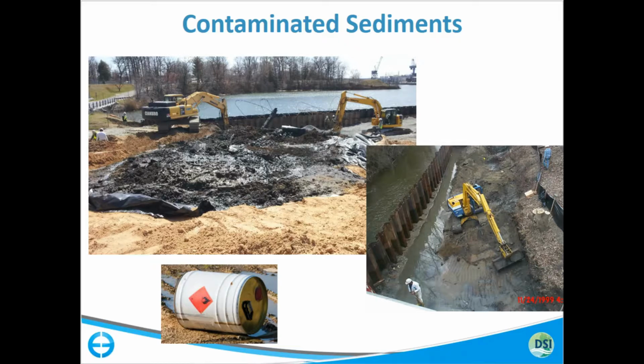But it's these chemicals, these organics. They attach themselves to sediments, and so pretty much where the sediments go, a lot of times, that's where your contaminants are. So if you've got an area downstream in a riverine system, and it's downstream of your toxic waste site, and you've got erosion that may have been occurring over the years, if you've got an eddy somewhere downstream, likely that's going to be a hot spot for contaminants, because that's where the material will have accumulated from anything that may have eroded off of the site.